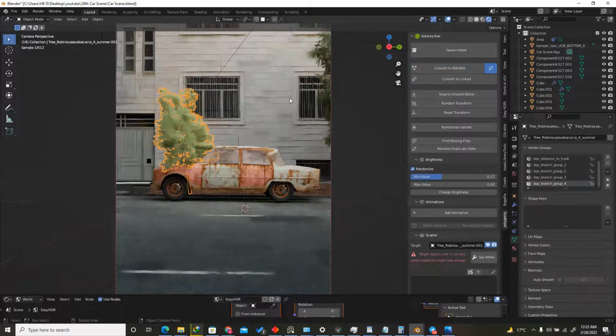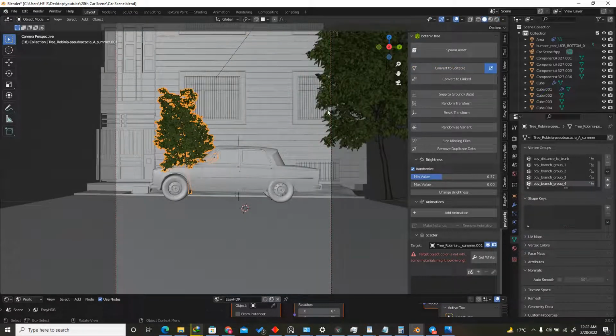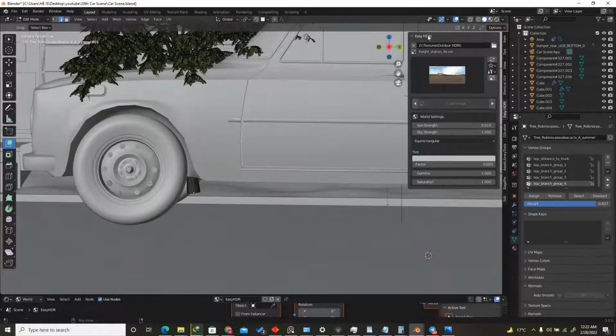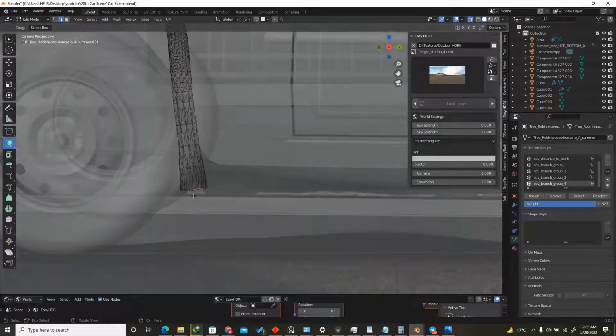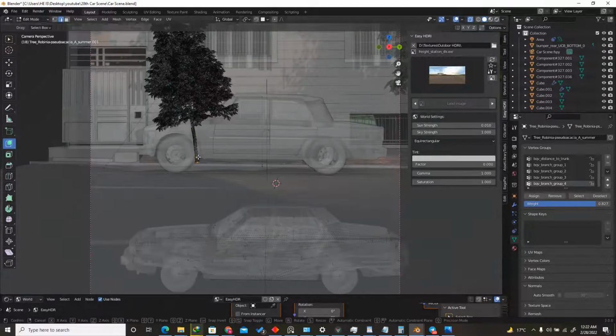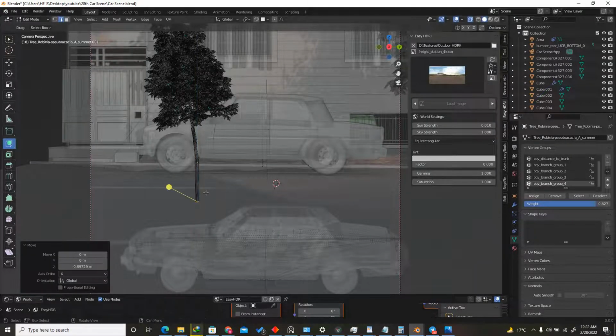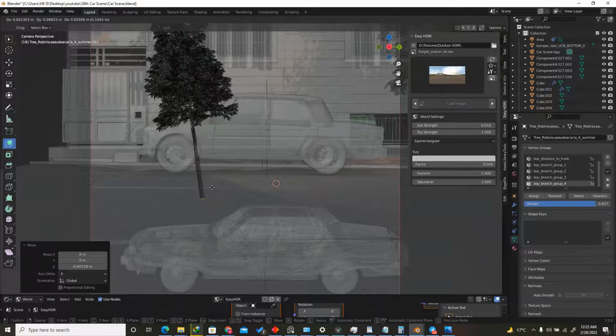After I have done that, let me go to the solid preview. Let me tap to get inside of the edit mode. After that, let me select this extra mode and make sure that the selection is this edge selection mode. I'm going to select like this, and then press GZ and move it in this location, and then press G and make it something like this.